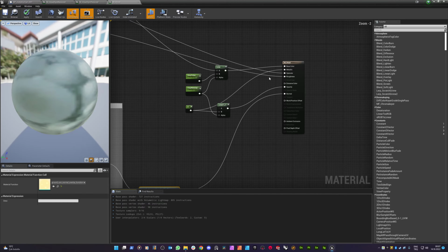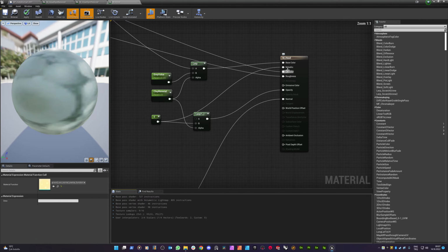But the one other thing to do is to manipulate the roughness value of the current material. You can either change the roughness value of this material to around 0, or something lower than 1, or you can just adjust the roughness parameter of this specific material as well.